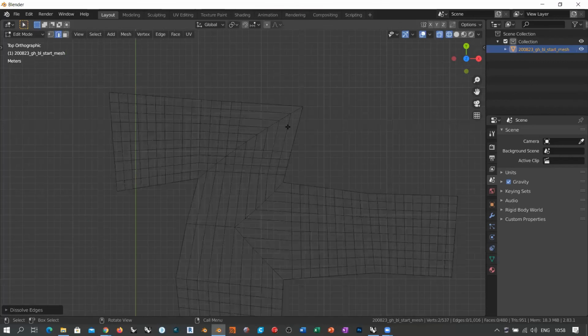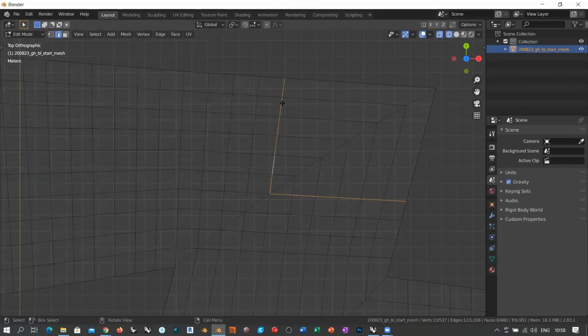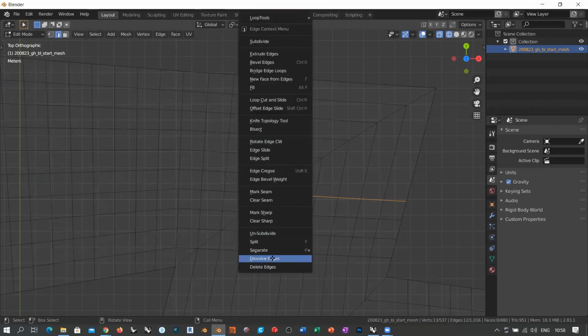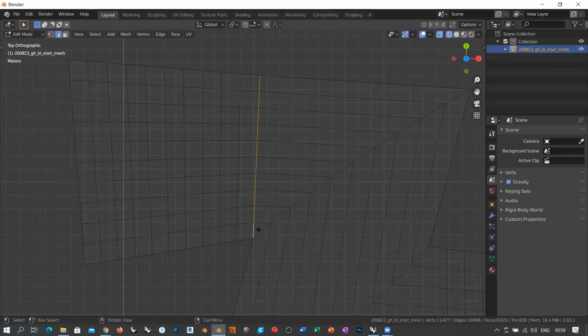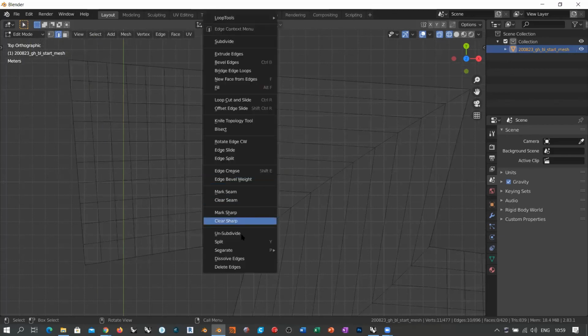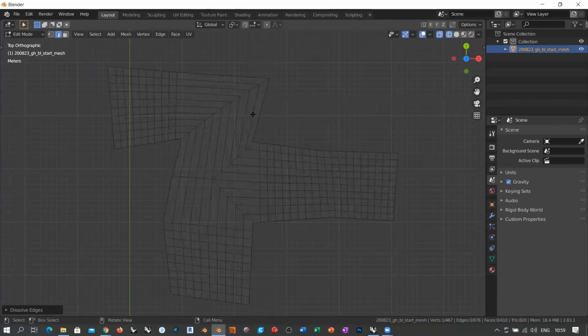So all these loops right now are turning left correctly. And then I concentrate on this, as it's the same basically. So remove this and this. If I remove this, remember, I must also remove all of these things here and all of these things here. So dissolve edges. And then these two here, dissolve edges, these two here, dissolve edges, and these two here, and dissolve edges, and also this, because here we have a pentagon. Okay, so right click and dissolve edges. So this is the final topology that we can consider for our mesh.